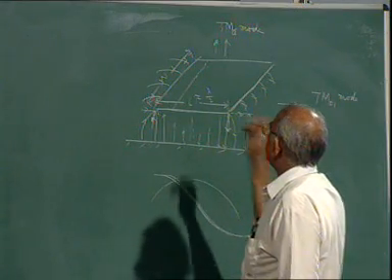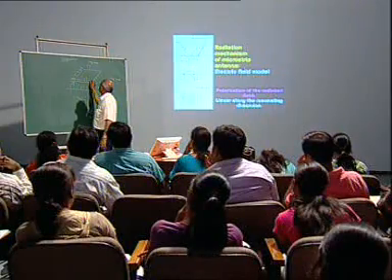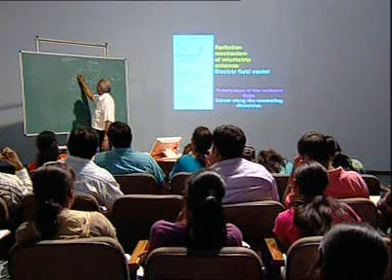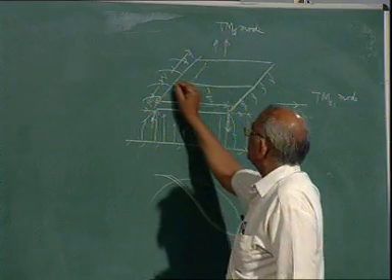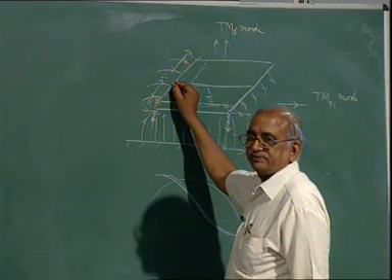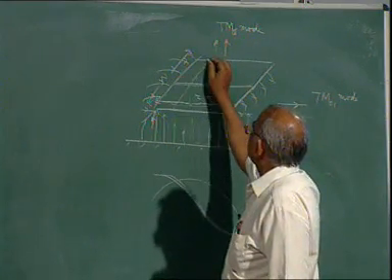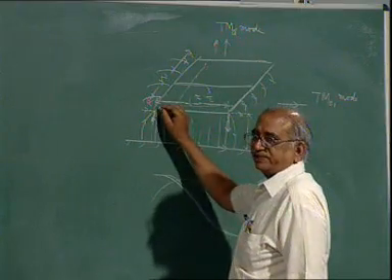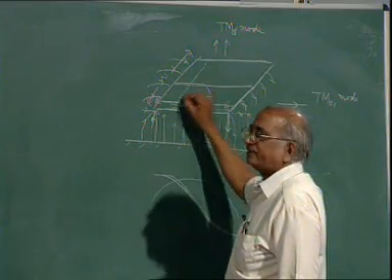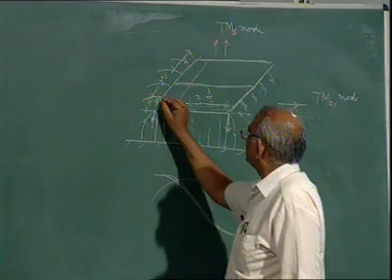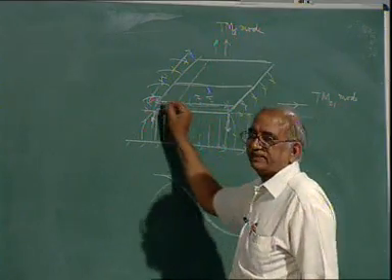Yeah, you have to feed along one of these lines, because at this bisector line the impedance is going to be 0. For this particular mode the impedance is going to be maximum over here. In between it is going to vary. So, you have to feed somewhere along a line like this.